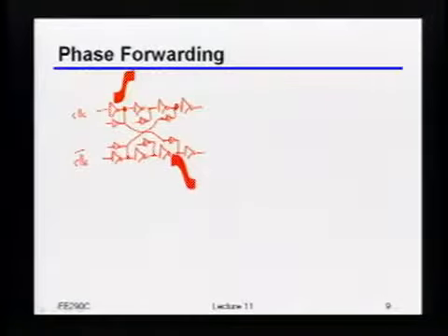So in other words, what we're doing, because we know that we will eventually tie a ring around this whole thing, and because we have a signal that's earlier in time, is trying to use that signal to speed this inverter up.